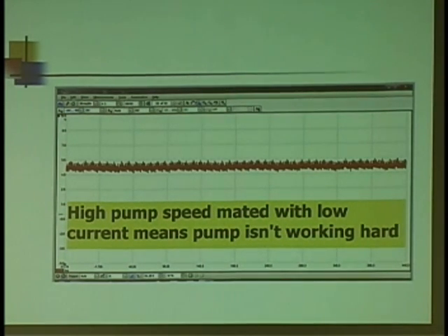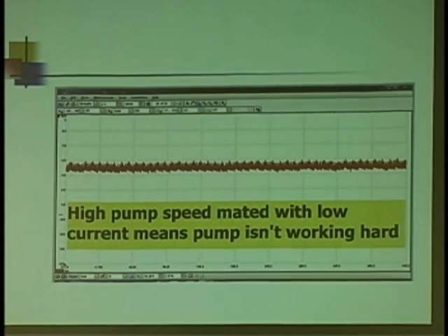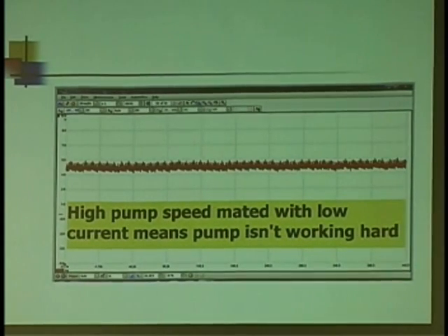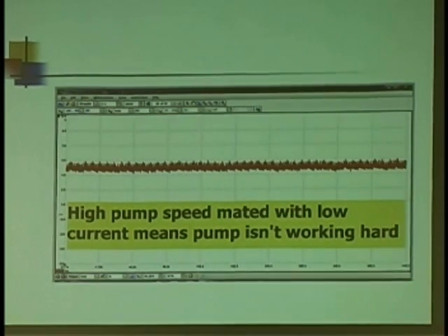Anybody ever have a no-start get towed in? It's got half a tank reading on the gauge, but it's out of gas. Yeah. We wonder if the fuel pump's turning. We don't hear it, so we get out the big rubber mallet and start beating on the gas tank. You know, on newer cars, you can screw the pump up that way. If I throw a low amp clamp, I don't even need the scope, just a low amp clamp on my multimeter on the fuel pump circuit to see if any current's running. I know whether the pump's running or not.